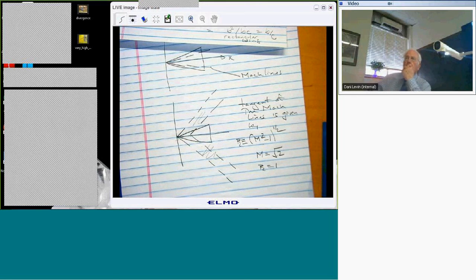And we've noted from time to time that when the Mach number goes to 1, whether we start from the subsonic side or the supersonic side, we get in trouble. Although, as I just mentioned, if we look at transient flows, at short times, everything's okay, even at Mach 1, according to this linear theory. It's only that if you're at Mach 1 and you wait long enough, eventually all those disturbances catch up with you and the theory breaks down.